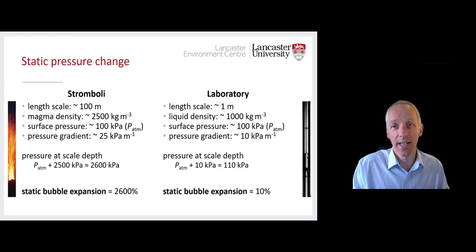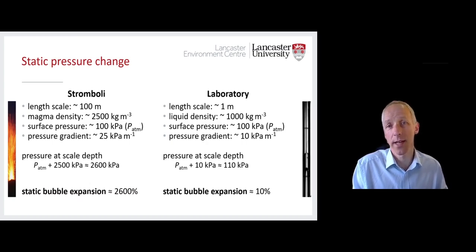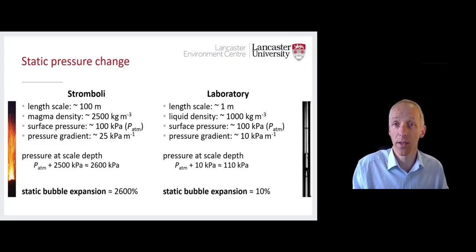Thus, there's clearly a scaling issue here. There are 2 orders of magnitude difference in what we would expect in terms of gas expansion over the model and the prototype length scales. So you might think of this as giving some sort of kinematic scaling issue. The relative change in slug length in the prototype is not well represented within the model.